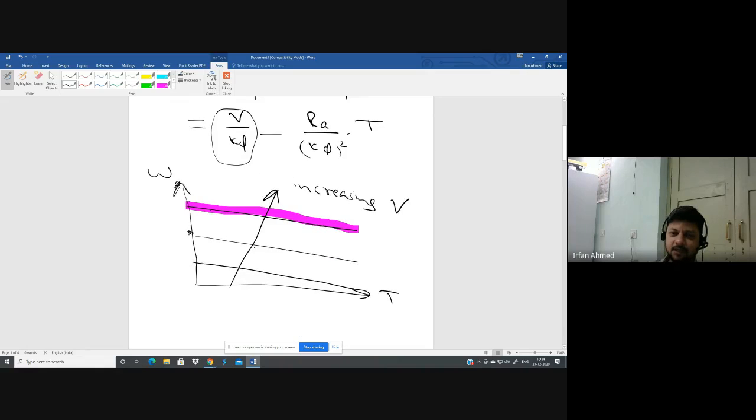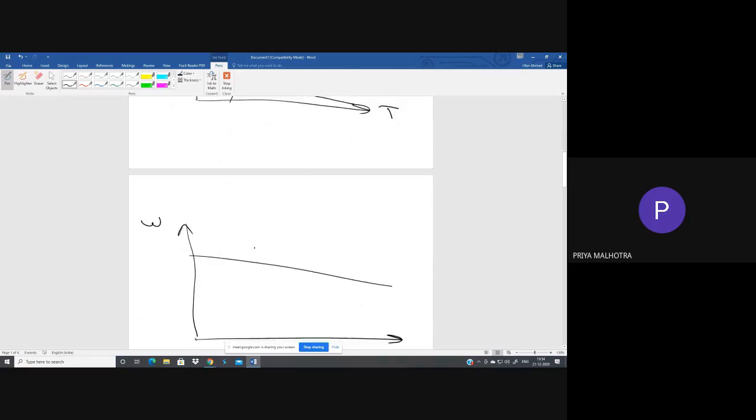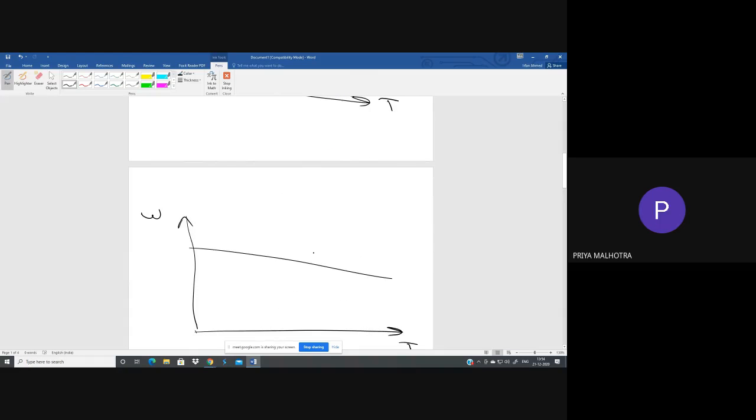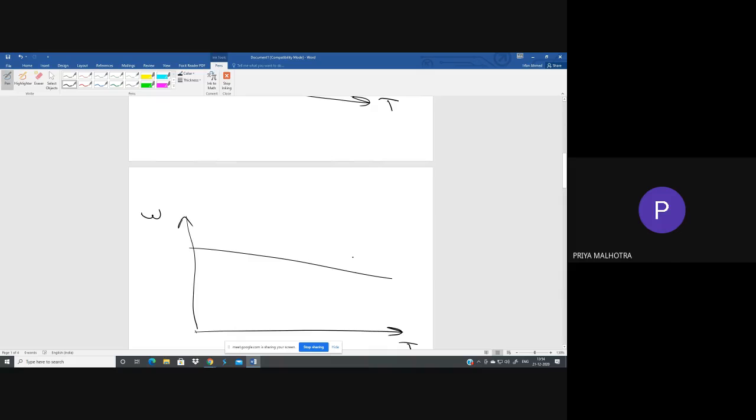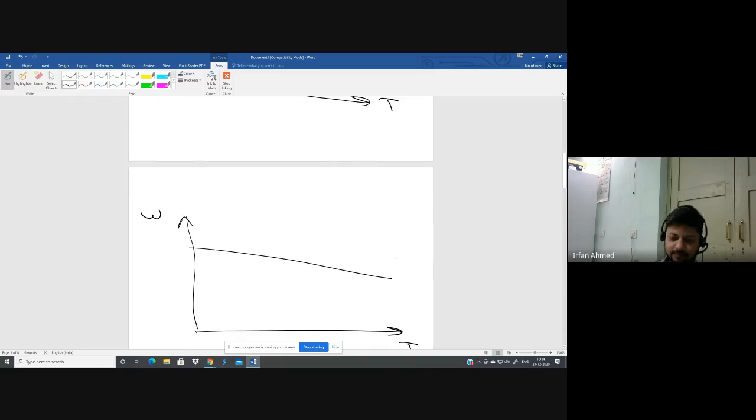Correct? So if you want 2 to 2.5 times, in all types of DC motor, it depends on the mechanical considerations, who is making it, which manufacturer is making it. With a local manufacturer, possibly you may not be able to go above 1.5 times also, so it all depends.